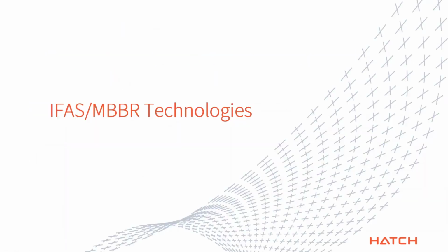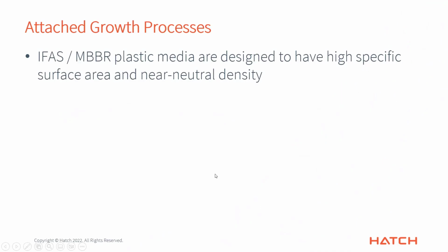Let's move on to talking specifically about IFAS and MBBRs. These are mostly what I'm going to talk about for the whole rest of the webinar today. So, of course, it's a very popular technology. And the idea is you have this plastic media, which you can add to existing tanks. These are designed to have a very high specific surface area so that you can get a lot of room for your biomass to grow in a small area or small volume. And somewhat near neutral density.